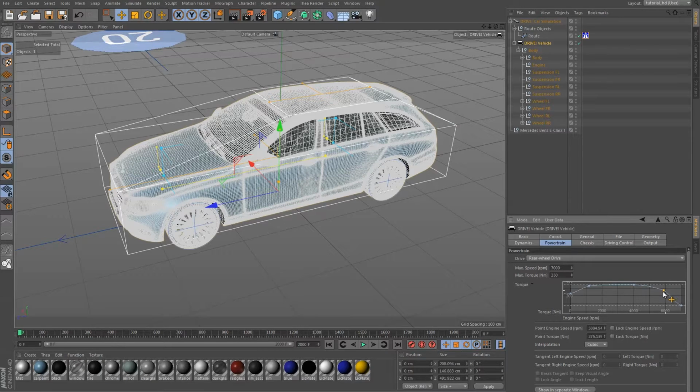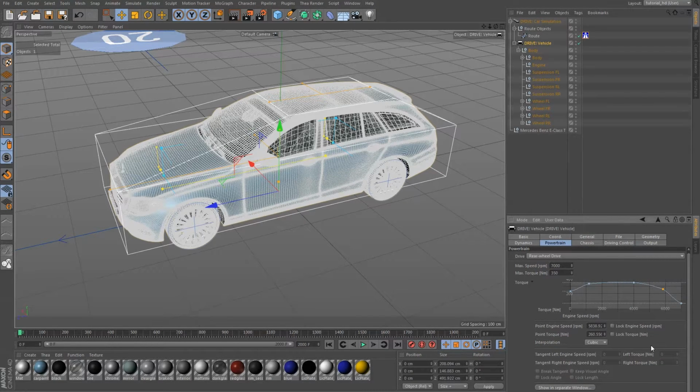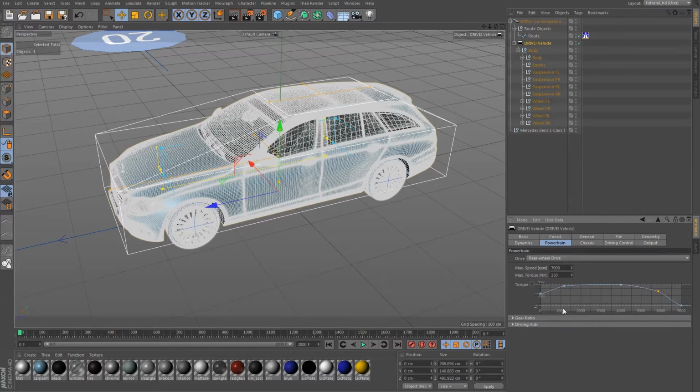This kind of shape can be seen for almost all modern cars. Old engines have a much smaller range for the maximum power. As a basis for the gear shifting range, you can inherit this range. So the gear will be shifted up if the RPM exceeds the maximum value and shifted down if the RPM is getting lower than the minimum value. If you want to achieve more gear shiftings, you can make this range smaller.